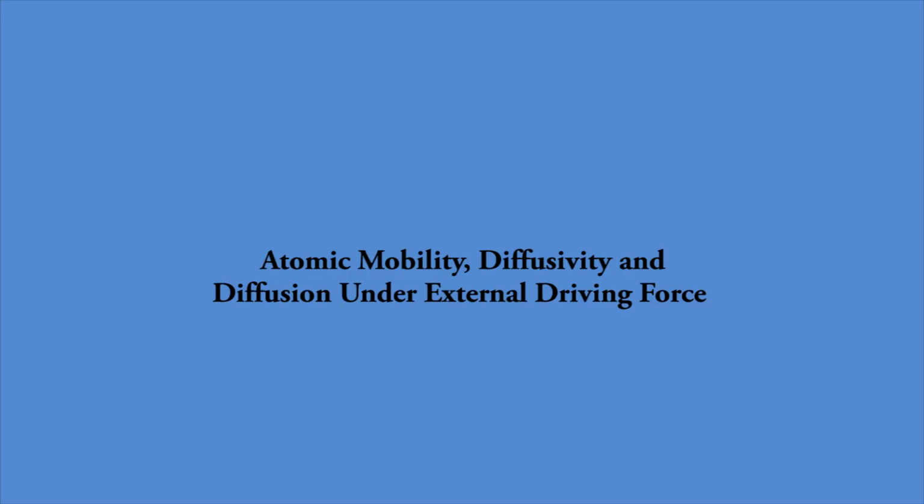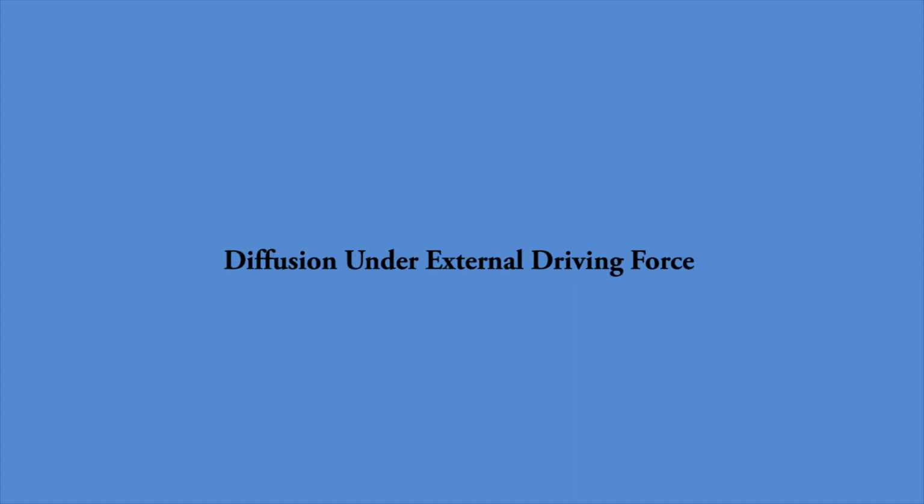Welcome to the 40th lecture in this open course on diffusion in multi-component solids. In this lecture, I shall derive the relation between atomic mobility and diffusivity. In this process, we will get introduced to thermodynamic factor. In the later part of this lecture, I will talk about diffusion under external driving force and derive the Nernst-Einstein equation. I shall also illustrate the application of this equation to the process of electromigration, that is, the process of diffusion under electric potential gradient.